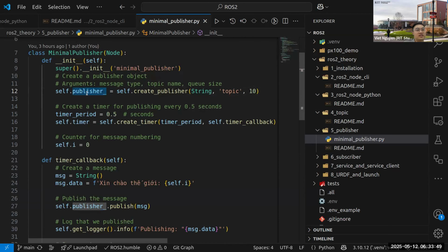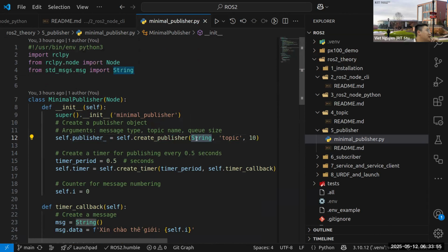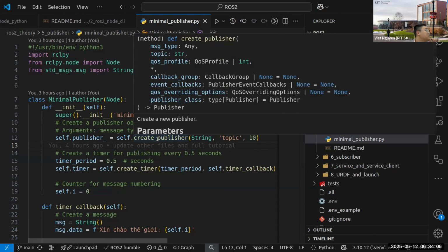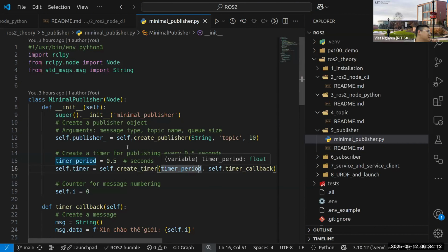And then inside this node, there's a publisher. When creating the publisher, first of all, we have to define what type of message we are trying to publish, and then what topic we are publishing to. And then this is the, I don't actually remember, let's see, QoS profile. I would guess this is some configuration regarding the spin time of ROS, but it's actually saying how much we are limiting ourselves of publishing below or above 10 milliseconds.